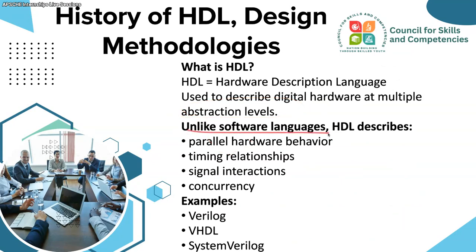Unlike software languages, HDL is different. Software languages go in a sequential way, but a hardware description language describes parallel hardware behavior. That is what you have to understand. It also covers timing relationships, signal interactions, and concurrency, where things happen concurrently. That is why it is totally different from software languages.